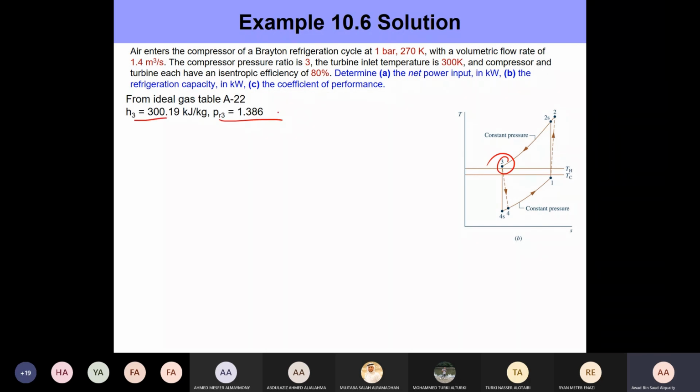And we consider the isentropic process 3 to 4S. Okay. And using this ratio of relative pressures to the actual pressures, which works out for only isentropic processes, we're able to determine PR4.